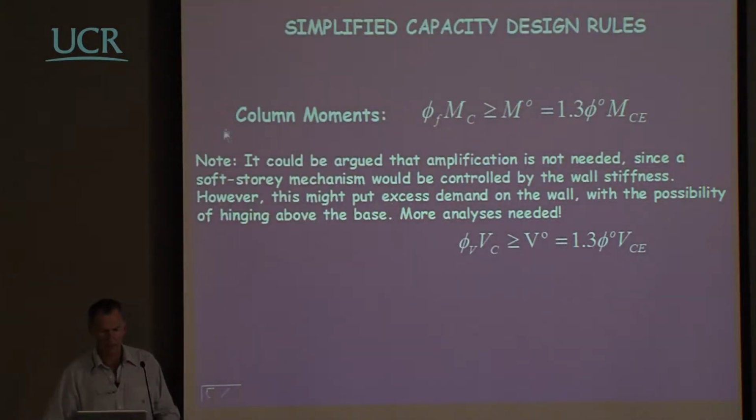So we could do it that way, or we could use some simplified capacity design rules. And in all the cases in the book of the different structural systems, we've tried to show the best, fairly simple, reasonable analytical approach to use for determining higher mode effects, and the second, to have simplified capacity design rules which are more convenient for straightforward design.